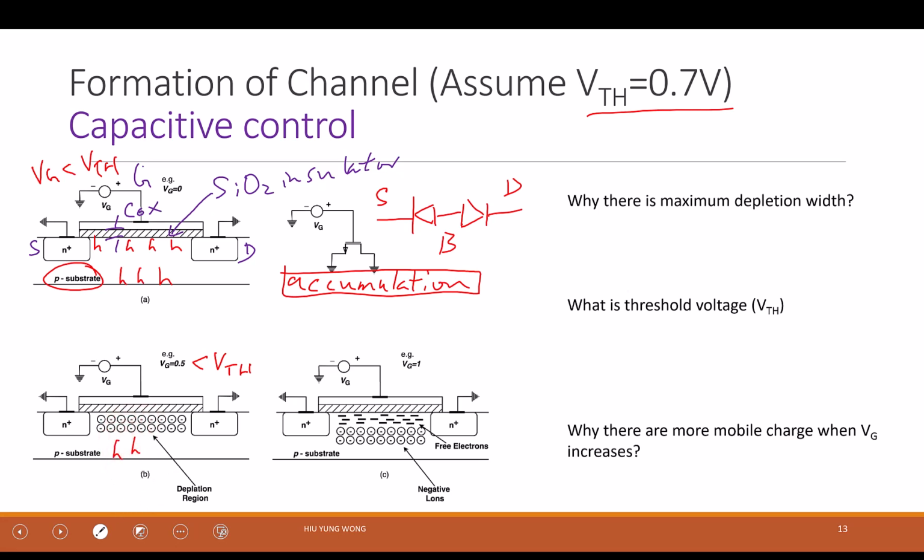But do you remember how you get a p-type doping? You actually have some dopant, and this dopant will release the hole, for example, the boron, right? So you will leave some ionized atoms, which are negative charge because you take away the hole, right?